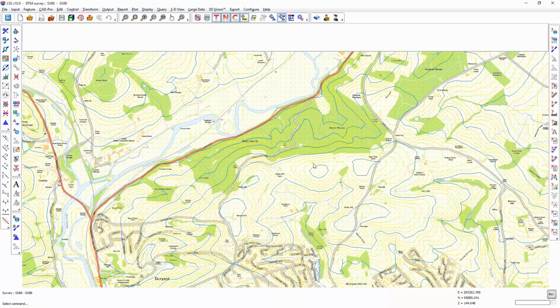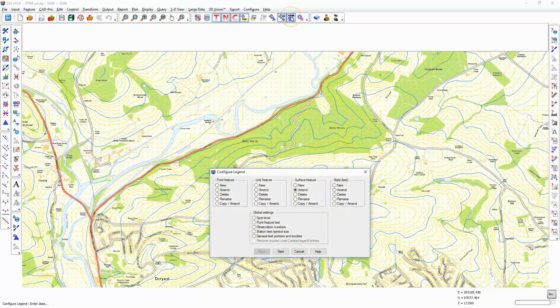What we're going to do is position some wind turbines on this hill, and we're going to use the ZVI ZVT visibility point feature command to determine from where within this terrain model those turbines can be seen. The first stage is to create some objects that we can add into the LSS survey. You can add these into your standard prototype and then use them every time, but I'm just going to create them new for this particular survey.